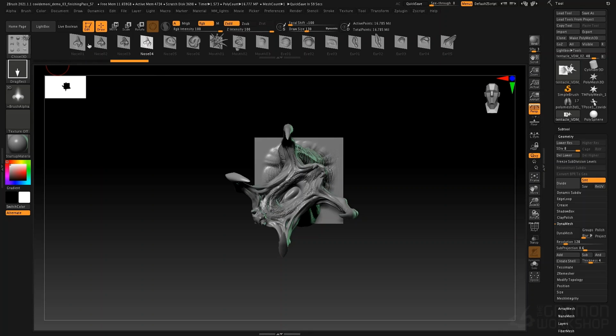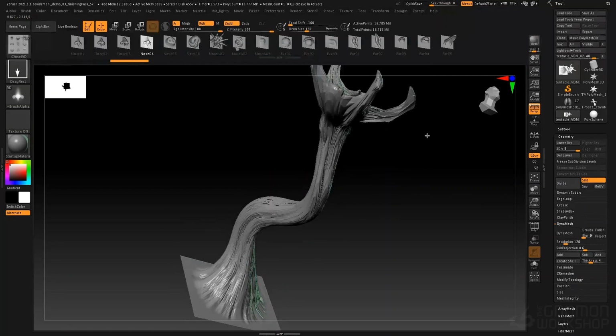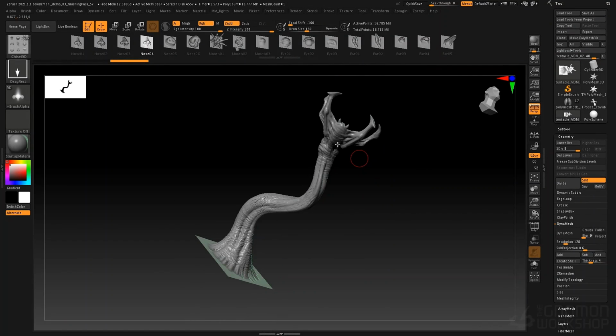Now you see that these brushes have a variety of planes like this associated with them already. There's eyes and ears and noses, and these are all very complicated protruding surfaces. That's the vector portion of the displacement brush. Most displacement mapping is done with a grayscale map or an alpha. It's shades of gray from white to black, and those can either push out or in. A vector displacement map, on the other hand, is RGB. It has 3 values, and that can be pushing around a 90-degree angle, so you can get very complex shapes like this.